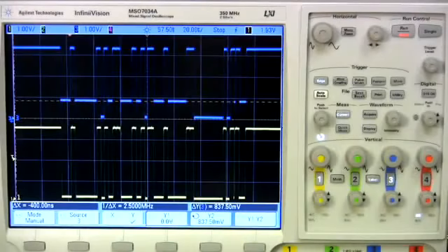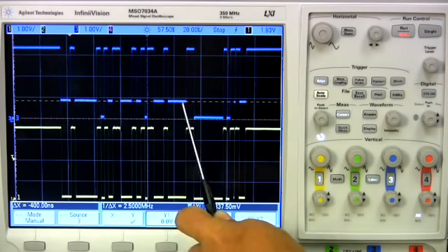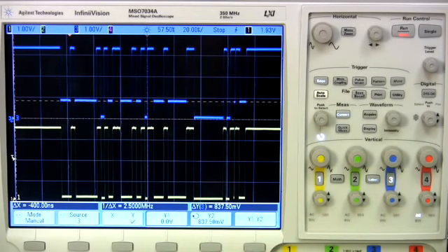Here are the SDA waveforms on each side of the isolator. The blue trace is the A side and the yellow trace is the B side. When the isolator is pulling down on the A side, it pulls to VOL. The SI3452 pulls down on the SDA during the acknowledged portion of the I2C waveform. When the SI3452 is pulling down on the A side, it pulls to a voltage slightly higher than ground. The isolator VIL is centered between the isolator VOL and the SI3452 VOL. This allows the anti-latch circuitry to work.